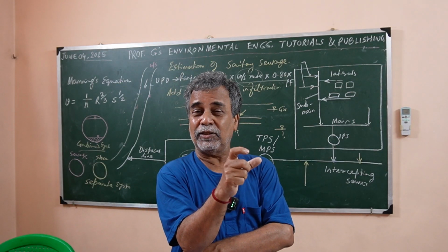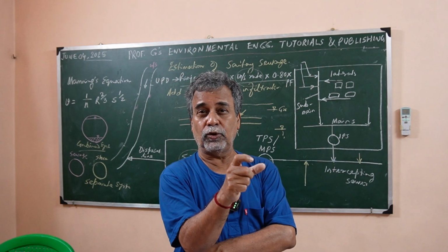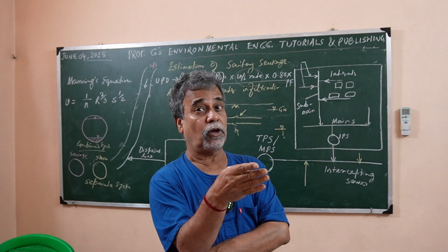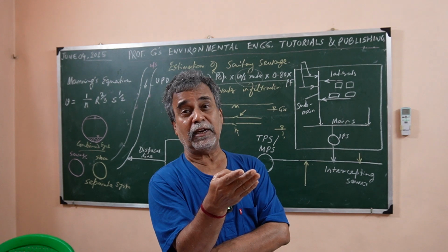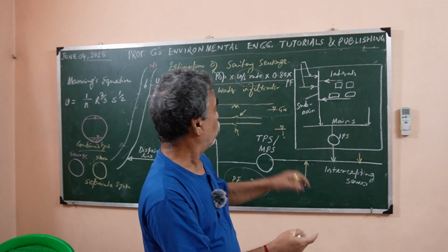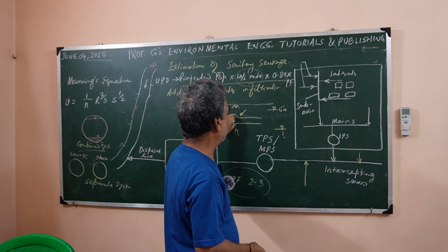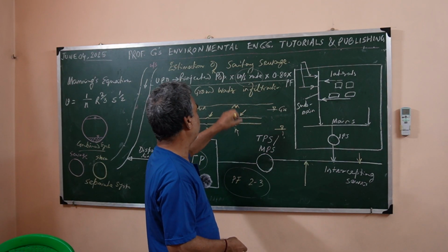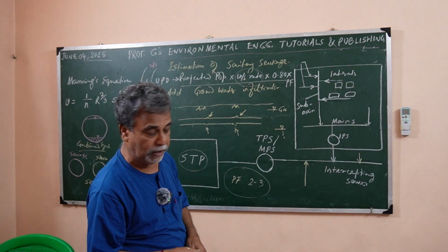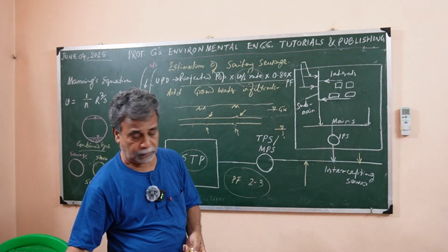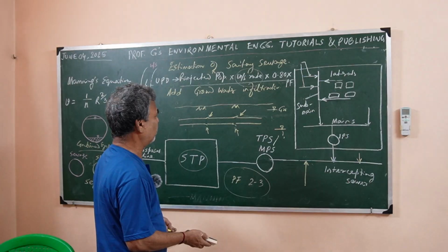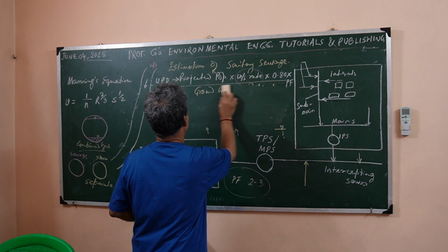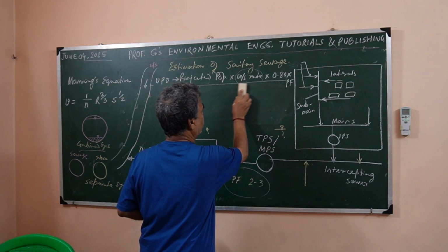while considering that the sewer lines are watertight as much as possible. Maximum water tightness can be achieved by good laying, jointing, and other workmanship. So you add groundwater infiltration accordingly, and this is added to find out the total sewage flow for which the system is designed.